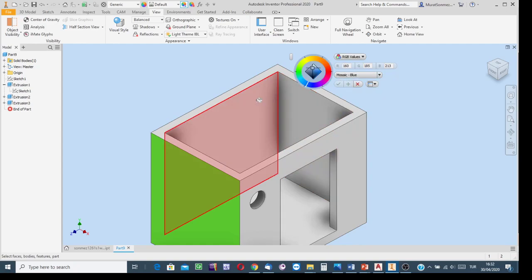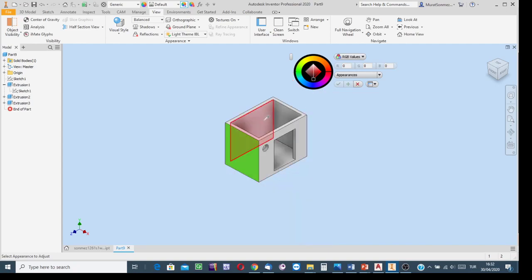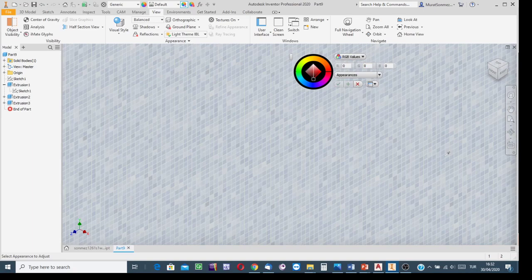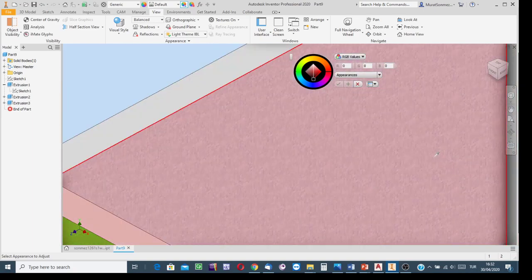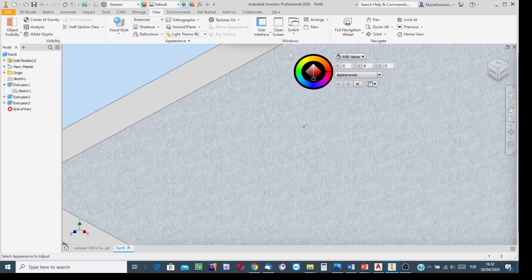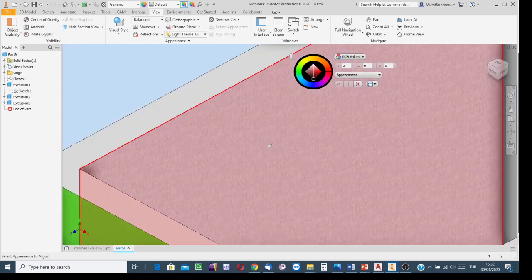Select blue mosaic and indicate the surface and then say apply. And then zoom in, zoom in. Yes, you can start seeing the mosaics. Can you see? That is the way to follow for having a surface effect such as mosaic cover. And then, well, deal with the rest.